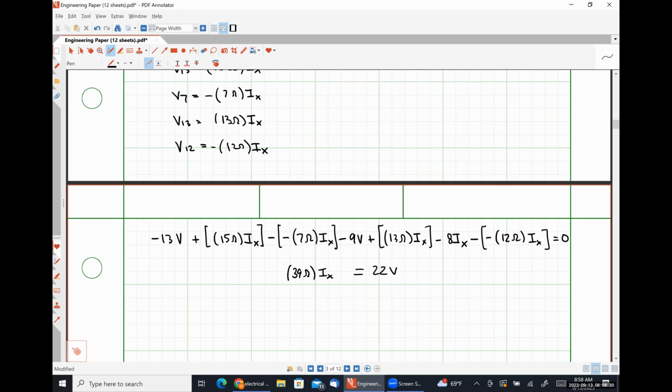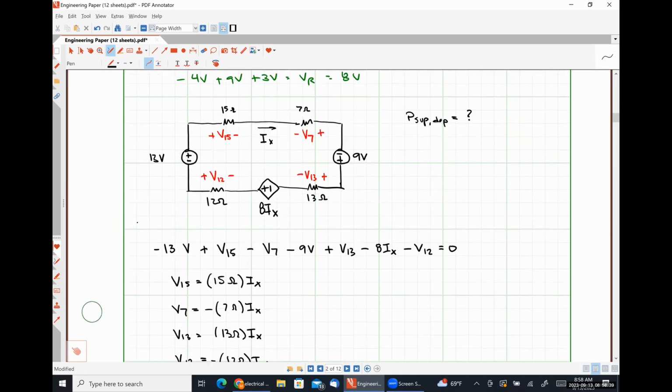Why is it okay? Because we have a current controlled voltage source, right? So the units on that quantity 8 are measured in volts per amp, which is the same as the unit of resistance, an ohm. So that's why I can add those together, even though it's not technically a resistance. It still has that same linear relationship between voltage and current as all of the resistors do.